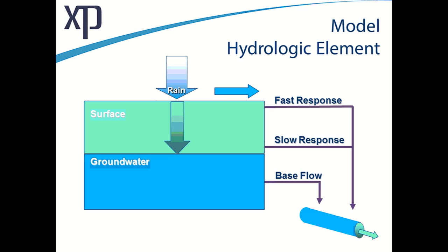And when we start talking about modeling, we have to determine what we want to do for subbasins. Typically in a combined sewer system, we look at modeling with at least 2 subcatchments. Now in XP Swim we can have up to 5, but we'll want to do at least 2, where one will be basically everything but the roof drains, because typically in a combined sewer area the roof drains are connected.